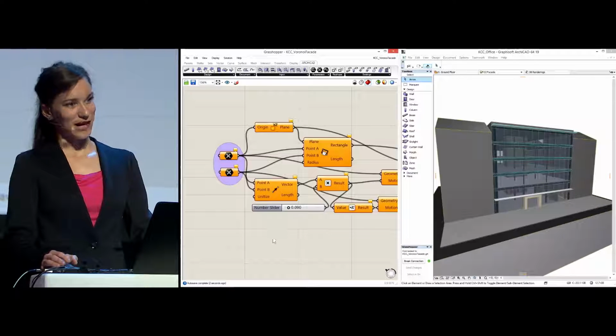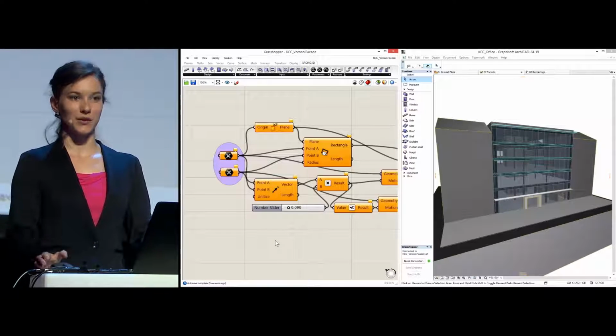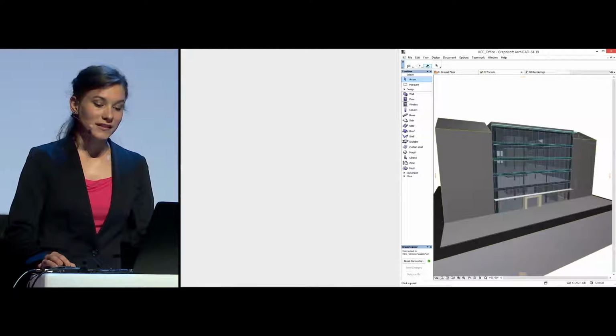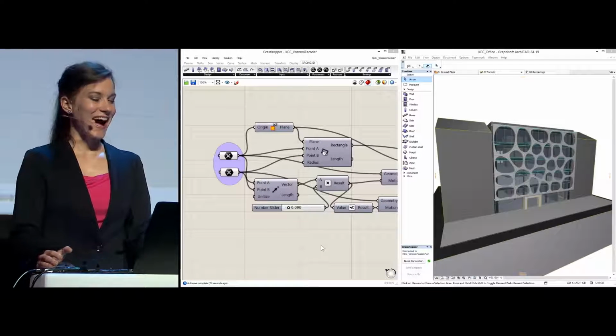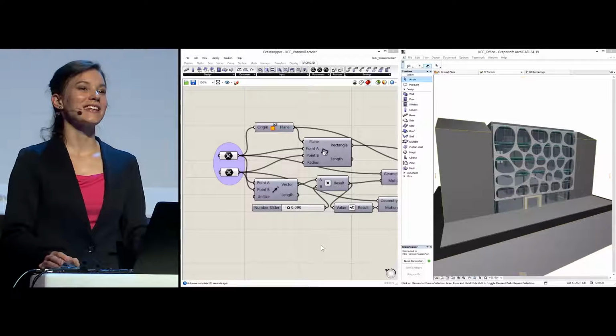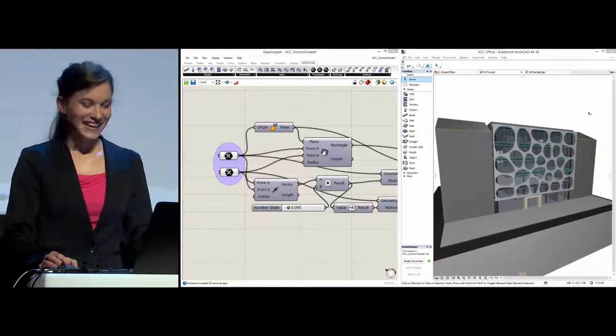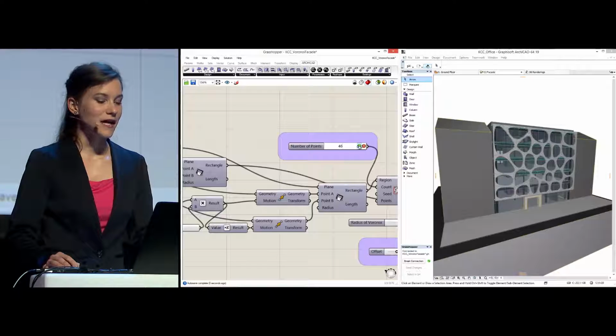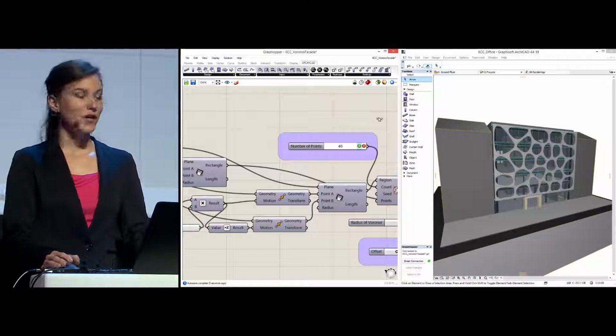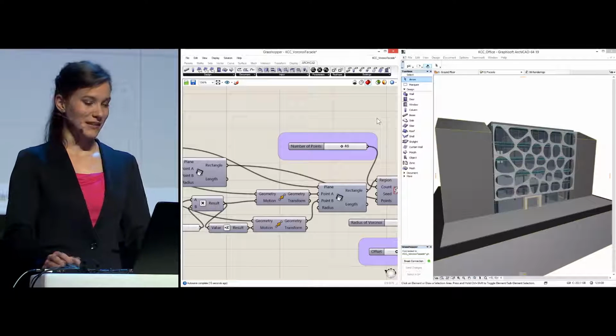Well, I have created the Grasshopper code, but in this case, I won't use Rhino at all, because I only need to pick two coordinates from my Archicad project. So remember, I am now referencing Archicad geometry. And as soon as I define those coordinates, the new shading system will appear in Archicad. And with the help of our parameters here, we can fine-tune the pattern anytime, again saving a huge amount of design iteration process.